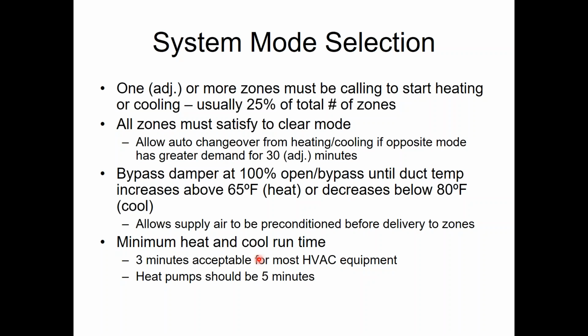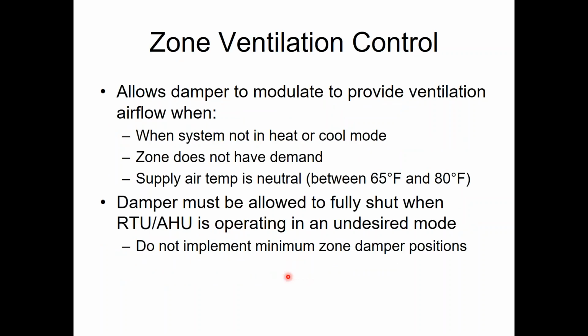You have a little bit of gap between there, and 5 is pretty good. Most buildings end up with a 2 or 3 degree gap. But 5 would be great if you could do that, Mike. I don't know that most people will function that way, but it'd be great. And then we'll have some limits on there for timers to make sure we don't switch over from a time standpoint too quickly. And usually the equipment nowadays has its own limits as well in that regard.